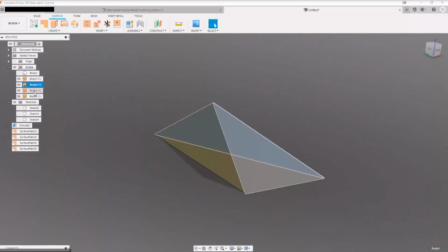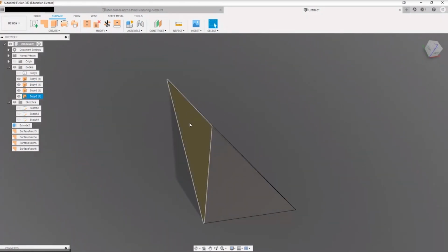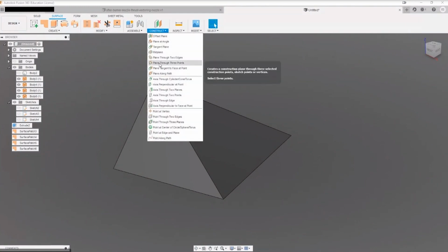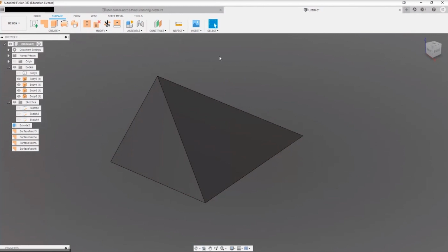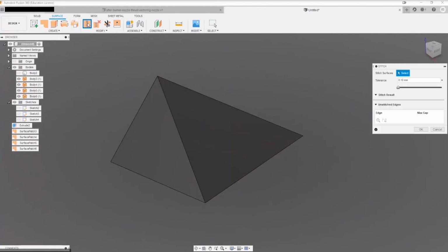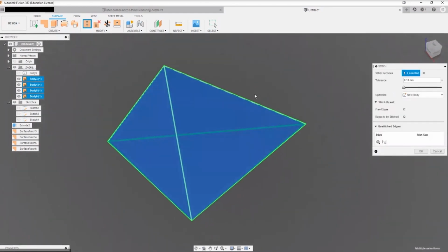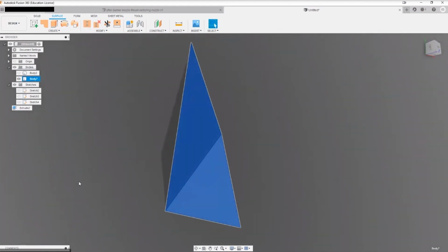What we see here is that we've got 3 different surfaces. Now, like I said, if you wanted to create a complex solid body, and you didn't want to chop it out of bricks because you wouldn't be able to calculate the different intersection points using the construction planes, so you have plane through 3 points and so on, these are almost like reference points. We're going to look at those in a moment. You can use this surface approach. And now let's just pick all the different individual surfaces and stitch them using the stitch function. All right, bam.